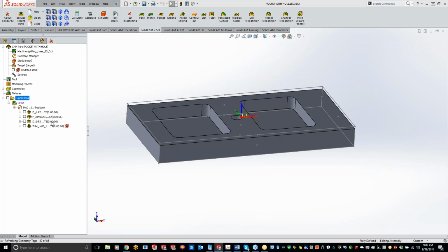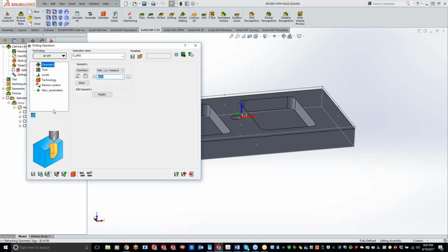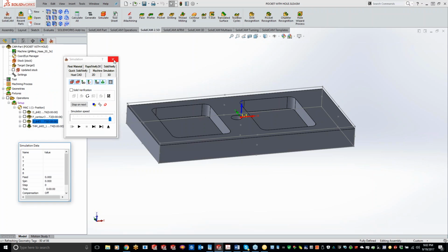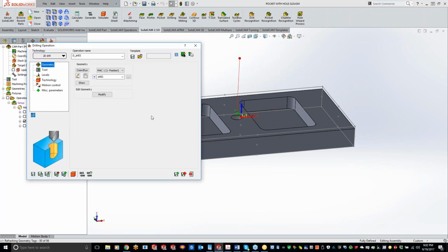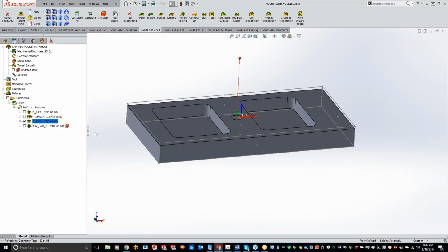And some of these I don't have times in here, and it could be just because I don't have a feed rate in there. Let's do a save. If we just do a save and calculate here. Yeah, it could just be. Oh, the drills blank out. Okay. So I'll get that turned in so we can get those drills showing up for you. But any profile, pocket, anything but drilling will show up with a cycle time for you.